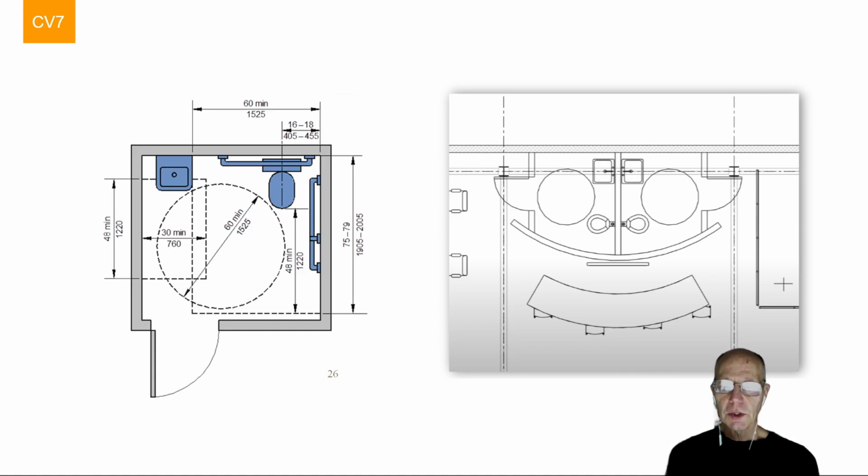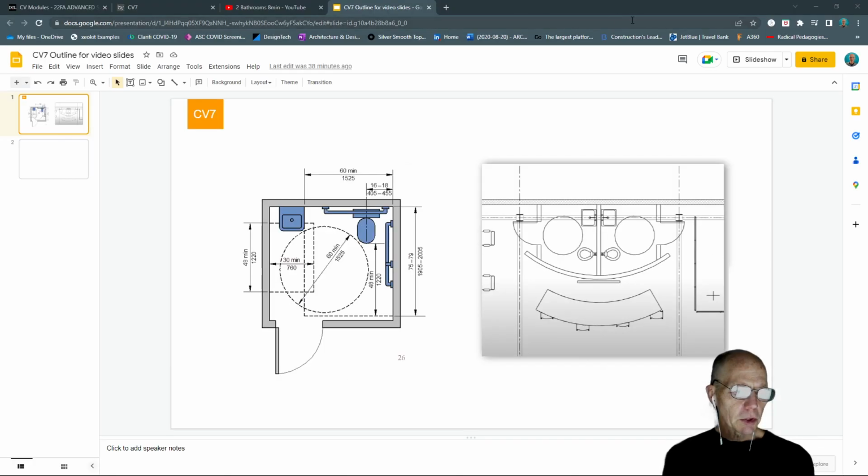And so we can do some very simple things by putting that turning radius in and making sure we have ample clearances, so that later on, when we may be just in the schematic phase or the early design development phases and have not laid out this bathroom completely to meet ADA requirements, we know we have sufficient room to insert those components going forward. So let's go ahead with that in mind and think about constructing our bathrooms in our project.